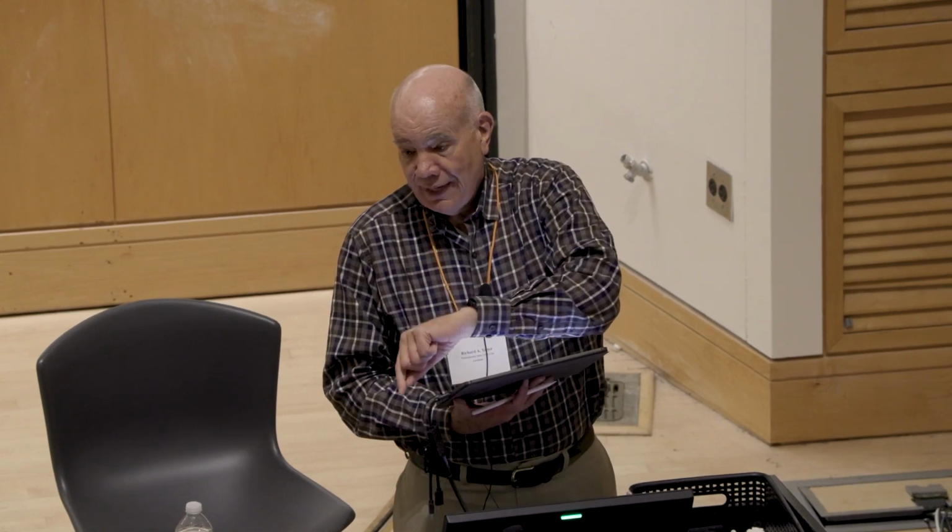One example that people have looked at is making a little hopping sensor. This potentially means putting a sensor out in a field, and it might sit out there for a long period of time, so that if I had an electrochemical battery, it would dissipate. But if I store the energy in an energetic material, and tune it to a flash of light or something that happens, I could fire off the energetic material. That could create gas, and if this thing is sitting down in grass or something like that, it could hop up and get out of the grass and then activate a sensor.